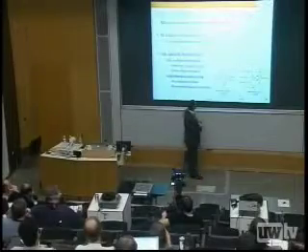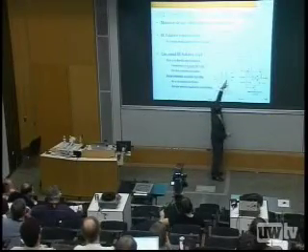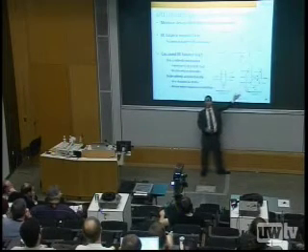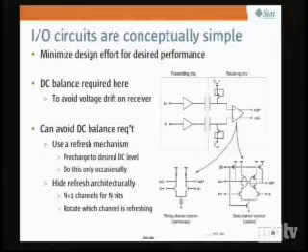And I can have circuits that are nothing more than a pair of inverters driving a capacitor plate. On the other side, there's nothing more than a StrongARM latch. All right, so NMOS diff pair, cross-coupled inverters, and a clock for a tail device. Very simple. Now, I do have to worry about things like offset, and I have to worry about how I clock this.